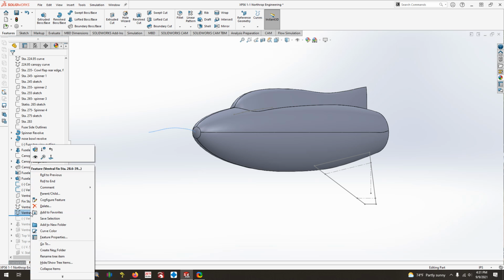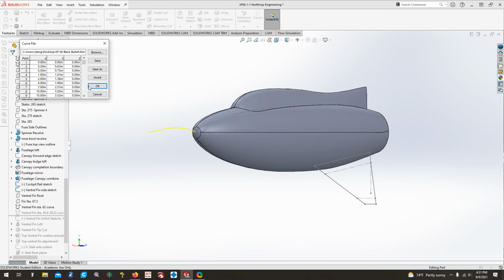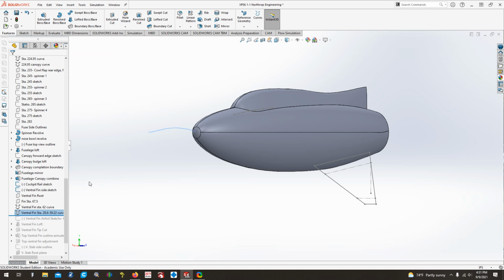One thing I did change, the documentation says there is a 50 thousandths thickness trailing edge, a radius. Since this is going to be scaled down to an 1/8 and a quarter scale size, instead of making this 18.18 here, where at the very tip would be 0, I went ahead and added that 50 thousandths. So by the time you do 50 thousandths on both sides, it's a 1/10 of an inch, so just under 1/8 or about 3 millimeters. And that would just make it a little bit easier when it comes time to draw the smaller scale fuselage, or I'm sorry, the wings and the ventral fin parts and the structure.